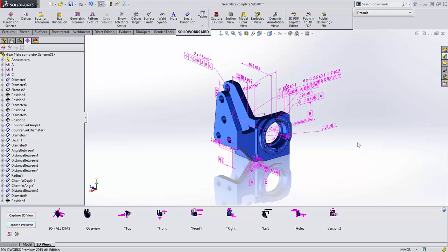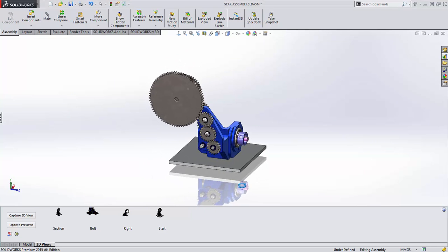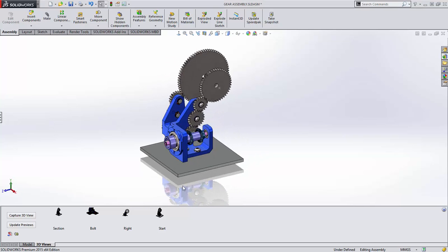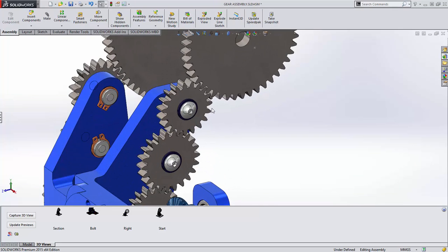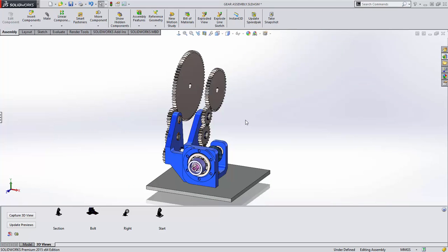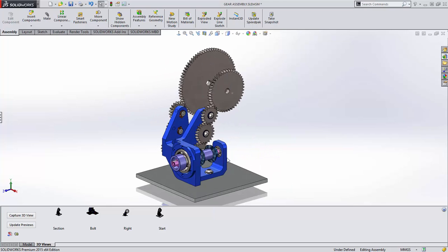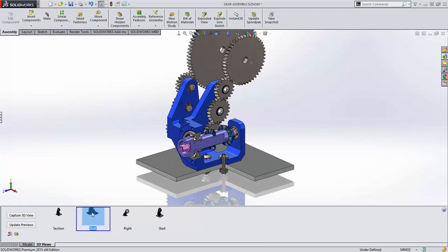In an assembly like this underwater camera housing, where precise fits are required to prevent water ingress and where these gears need to mesh accurately to control zoom and focus, every part needs to be machined to a very tight tolerance. This can mean high costs, but carefully considered geometric dimensioning and tolerancing can actually lower costs in some cases. So GD&T is not just for close tolerance parts and assemblies, it can be applied to any part.